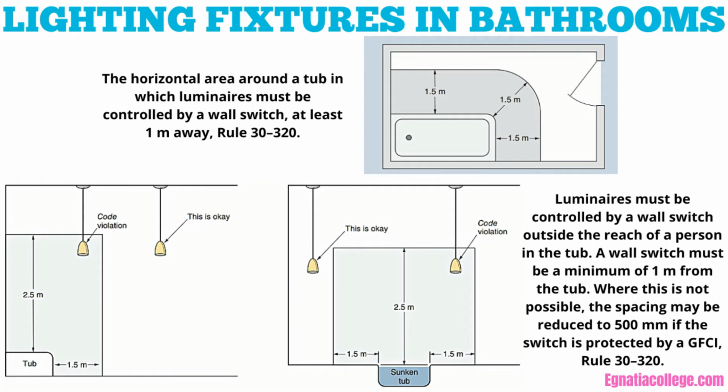The switch must be located at least 1 m from a tub or shower so that a person standing in the tub or shower will not be able to reach the switch. In installations where this distance is impracticable, the CEC does allow us to reduce this distance to 500 mm. However, the circuit must be ground fault protected.